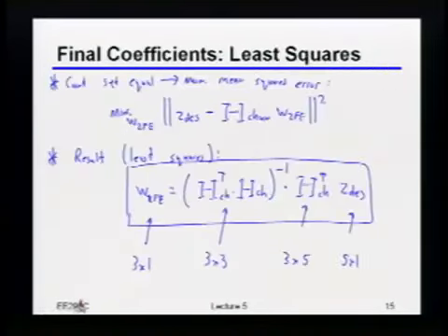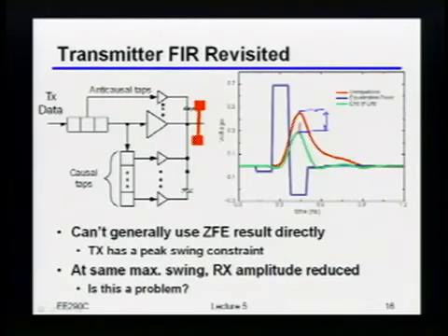And actually, I guess this one shows it too. So if you've got a dispersive channel, it turns out you tend to have a lot of junk right next to you. Right? And in particular, that first post cursor tends to be pretty darn big. So a lot of times, if you did that, you kind of lost a lot of the advantage of doing the DFE in the first place. So if you looked maybe about 5 to 7 years ago, you would see a lot of these solutions that had so-called gaps in the equalizer space, where the DFE just couldn't actually cover it. These days, almost all of them, if they have a DFE, they're covering the things close by you, and then maybe they're covering things later on.